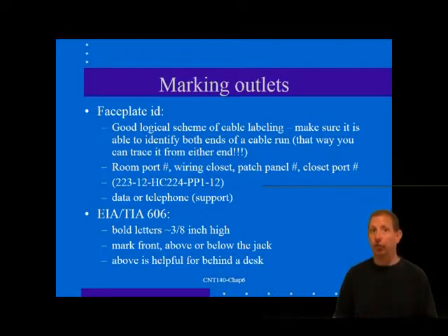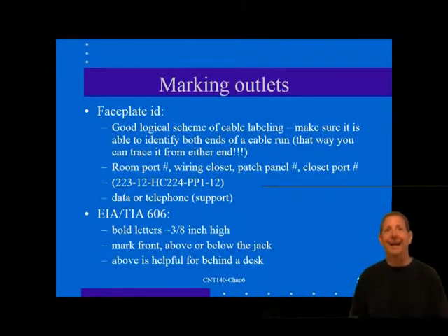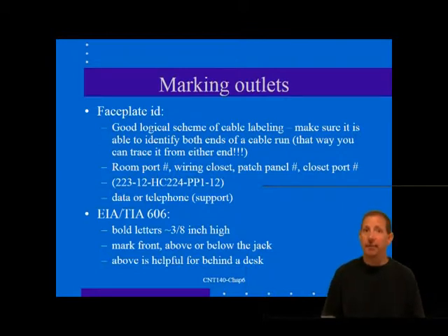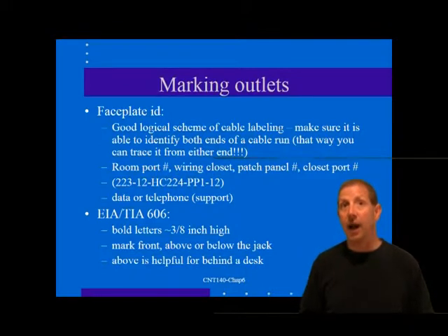Telephone extension numbers generally should not be marked on the plate, since many phone systems allow the number to be assigned to any physical outlet. The same applies for data jacks that correspond to a particular port number on a LAN hub or other network connection. Cable numbers count, however, as you must be able to read the cable number later.